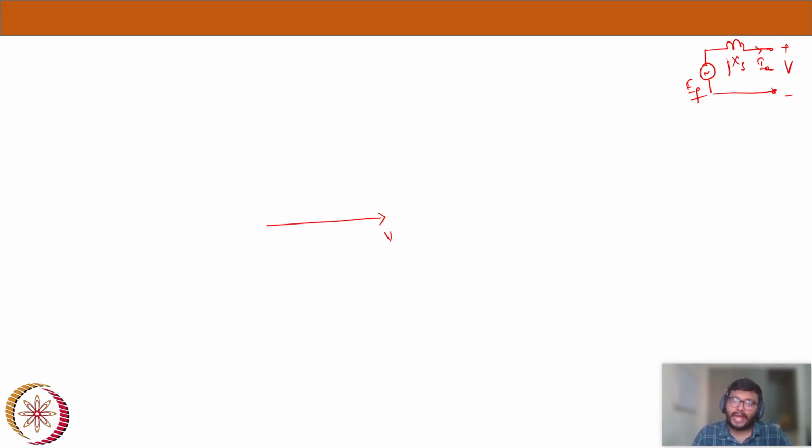Now at some excitation, I already have some excitation, and the field current is fixed. Let's say initially some excitation IF is already present. At that particular excitation, let's say my IA is here. Between V and IA, the angle will be theta, which is the power factor angle. Initially it is IA1 and the initial power factor angle is theta1.